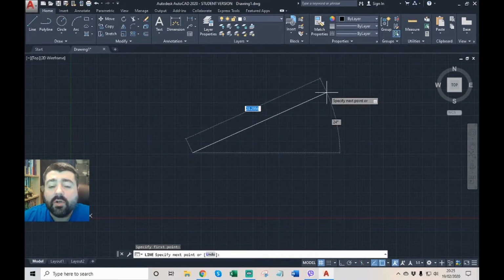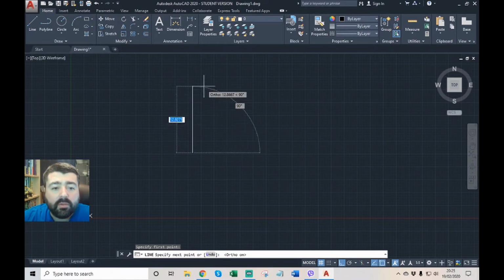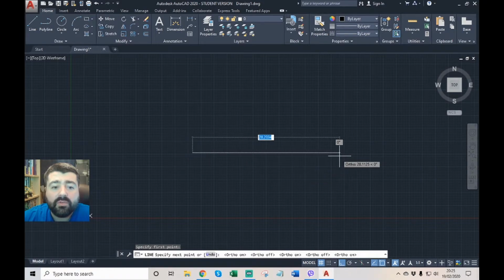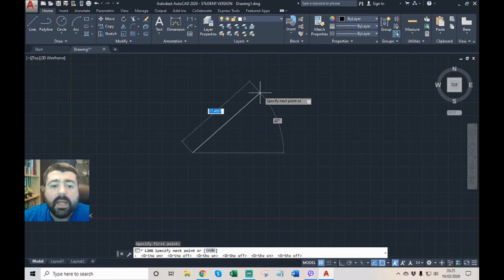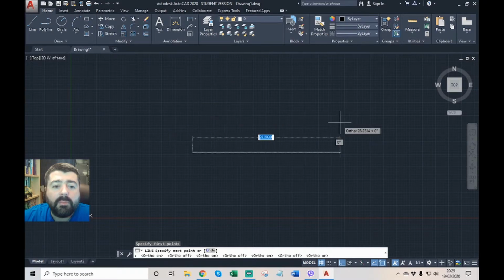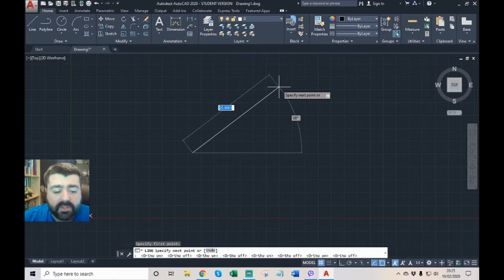When you drag your line, if it's only going either horizontally or vertically, that means you've got something called orthogonal, or ortho, which I've just switched on. You can toggle that by pressing F8. So if it's on, you press it to turn it off. That's very useful, and it's one of the features I use multiple times a day, switching between drawing lines wherever I want and drawing them vertically or horizontally, or orthogonally as it is.